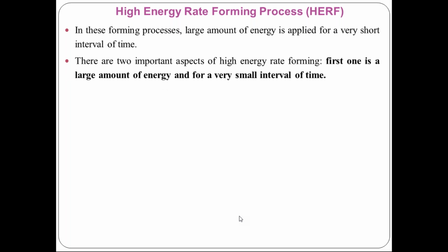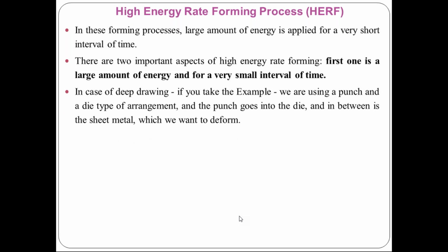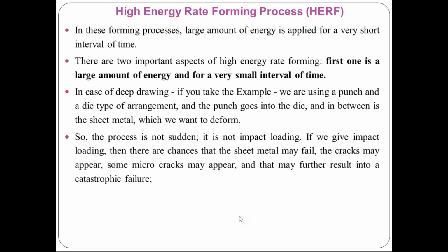There are two important aspects of high energy rate forming. First one is a large amount of energy and for a very small interval of time. In case of deep drawing, if you take an example, we are using a punch and die type of arrangement, and the punch goes into the die, and in between is the sheet metal which we want to deform. So the process is not sudden, it is not impact loading. If we give impact loading, then there are chances that the sheet metal may fail, cracks may appear, some micro cracks may appear, and that may further result in catastrophic failure. That means you will get the two parts separated